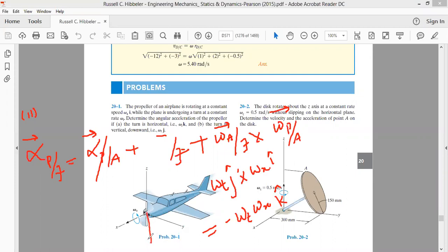Angular acceleration is along the z axis. Okay, if we put our thumb in the downward direction, then our fingers curl in this direction. On this plane, it means the aircraft, which was initially moving along the x-axis, as the aircraft is now tending to move downwards, what will happen? It will not only move downwards, but it will rotate. The entire aircraft will undergo rotation about the z axis. Okay, so this is all about the gyroscopic effect. So the student should be in a position to decide whether the nose will go up or the nose will go down. But the way of doing it is not simply making guesses by intuition, no, but by solving the kinematic equations. Thank you very much.